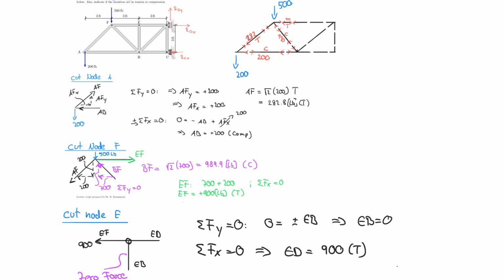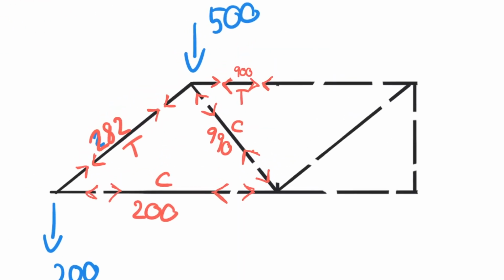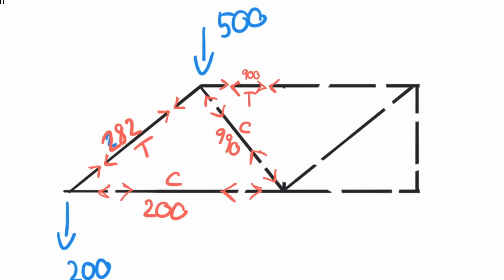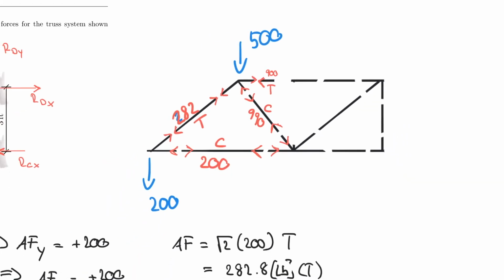And in fact, if I zoom into my sketch here on the top, it's almost pointless now that we erased the vertical member to have these arrows here. So I'm going to remove them, and I will make them just one big long member, if you will. So let's look at that. So I really have only this, and now I know that everything up here must be 900, and here this must therefore also be in tension. So I'm already done with that component now.